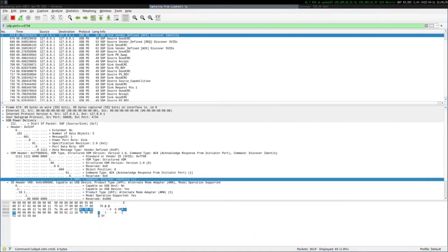I have a cursed portable laptop which has two USB connectors, wired completely in parallel except for the CC wires. Yes, so if you have USB-C connectors, it doesn't mean that you always have CC wires, or that the CC wires are completely parallel, or that you have power delivery. In the hub, one of the ports doesn't have power delivery at all. It has the CC lines to discover the orientation, but it doesn't speak power delivery. Don't try to connect the charger with a full-featured CC cable if you use a USB DisplayPort. Probably depends on the hub.